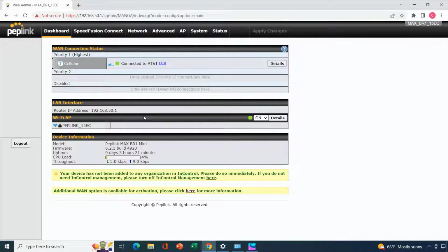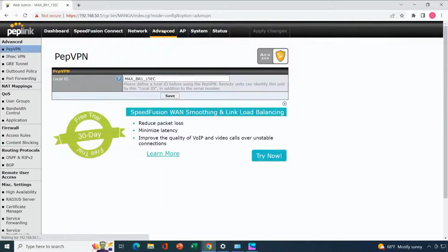Okay, now as I mentioned before, if we want this router to know where to send the messages when they come in, if we're talking WebMI type web browser messages or maybe Cscape for troubleshooting purposes, we need to tell the router where to direct the messages, and we do that through the port forwarding capability. And in a lot of devices, including this particular device, port forwarding is under Advanced. So if you click on the Advanced tab and you look over here on the left, you'll see port forwarding.